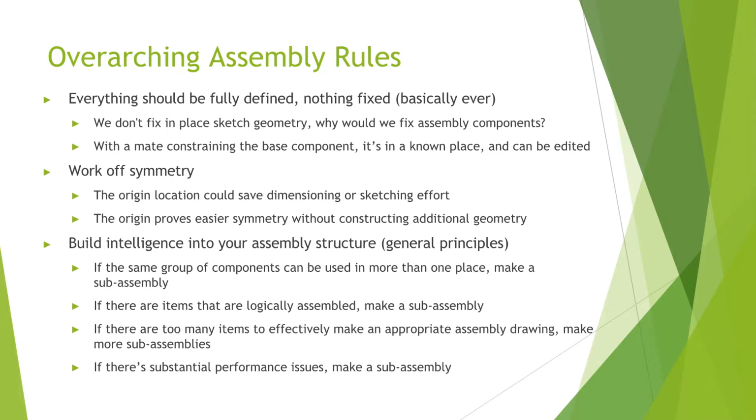With a mate constraining the base component, it's in a known place and you can edit it and move it. So one of the biggest problems, if something is fixed and you float it, you don't know where it was in geometric space. So if you move it, you don't know how much you moved it. If you want to move something over 1/4 of an inch from a fixed point, and it's not on the origin or constrained in some way, you're totally SOL, which is a problem. There are a bunch of workarounds, but.